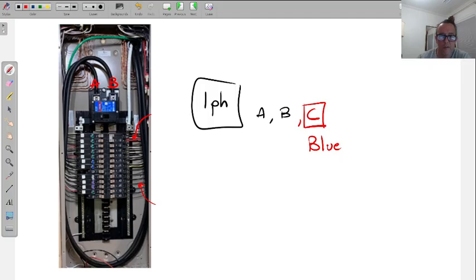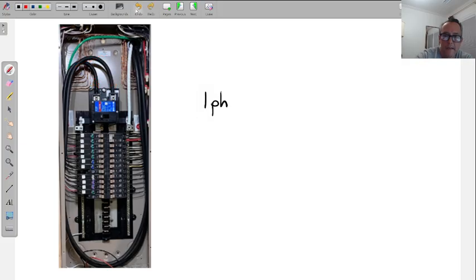All right, so there's a few things that I know. Also, we know that it's low voltage because there's a white neutral. There's another thing that is giving me some identification. And then we've got a couple of other things like the bare copper back here. This indicates low voltage versus high. But we don't have to get too far into the copper. Again, we can identify the low voltage because they're using a white neutral. There's a couple of red conductors in there. They're using black versus brown, orange, and yellow.